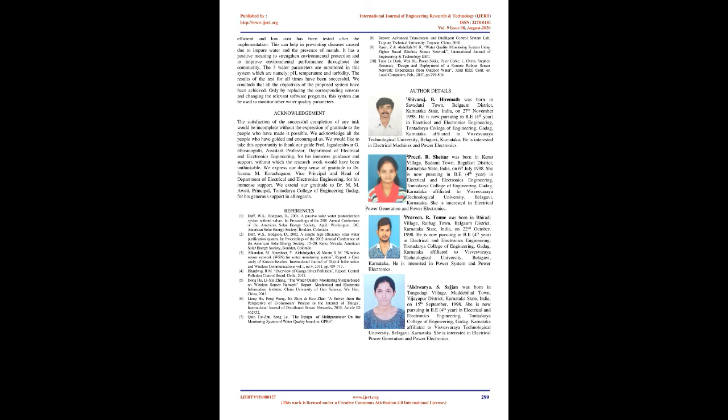Conclusion. This paper presents a solar energy-based water purification system using a density-driven method. The system presented is the density-driven system to include an oxidized copper pipe and a heat exchanger. The density-driven system has an advantage that it does not have a valve to maintain. With no moving parts to fail, the system becomes very reliable.